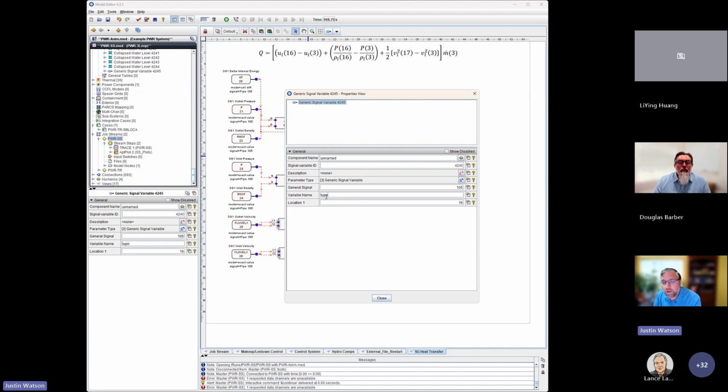To get through some input processors, all of these variables need to be preceded by LU. So if you want something else like the velocity of the liquid, so VLN, it would be LU VLN instead of LUP in here. And then finally, the location is the cell of the variable that you want. So the cell location. So for ours, this would be how we can get the pressure.